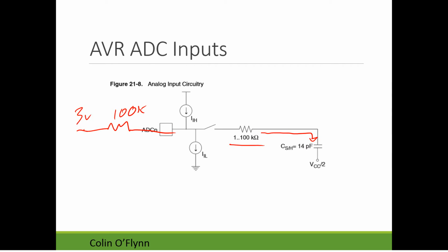But if you have a signal that goes 3 volts, 0, 3 volts, 0, 3 volts, 0, you're not going to see these sharp transitions. And so that's what it means when it says you should have a lower input impedance here, such that it's able to fairly quickly charge up that sample and hold capacitor. So that's sort of another related effect to circuit loading that you would care about in your system.